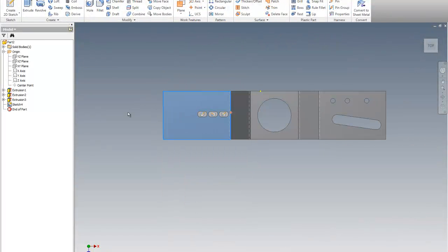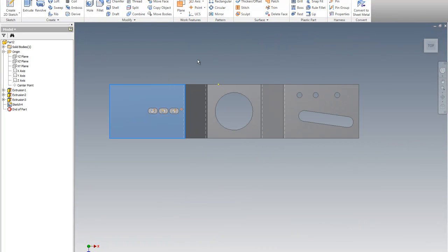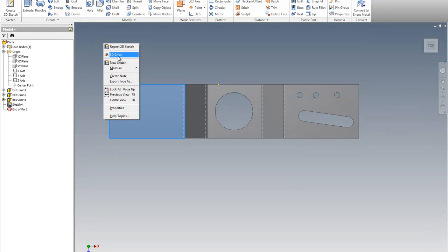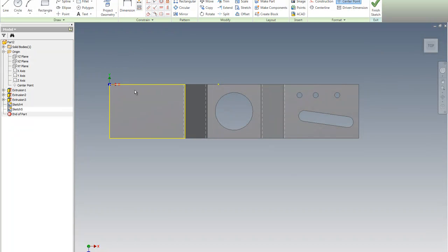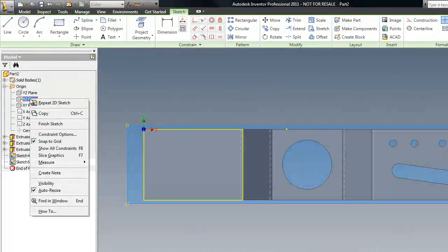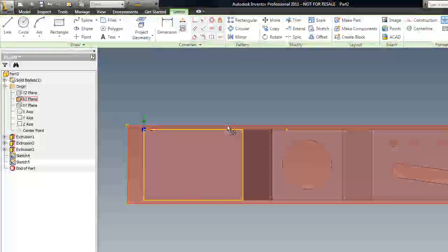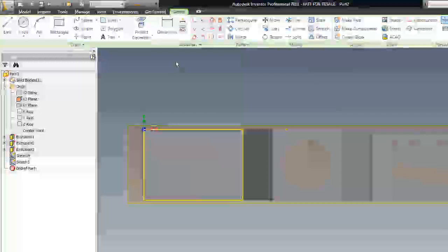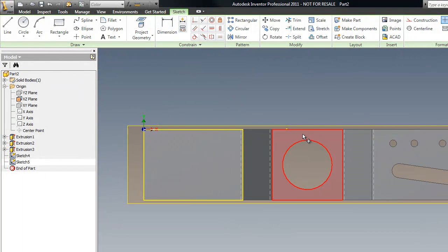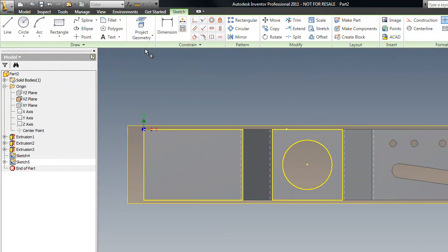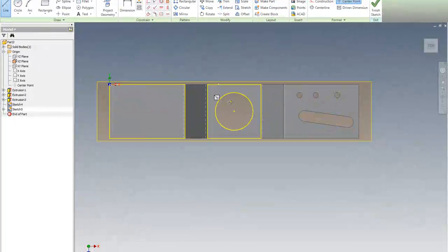And we're going to flip it over. And I'm going to go in here. And I'm going to go up here, and I'm going to go new sketch and pick this face. Okay? And then I'm going to go to the XY plane and show you that there we go. It's on that plane. Okay? So the first thing I'm going to do is I'm going to project geometry. I'm going to project this geometry that you see here. I'm going to create a line from the center point of that circle just up and perpendicular. Escape. I'm going to select that line and go to construction.